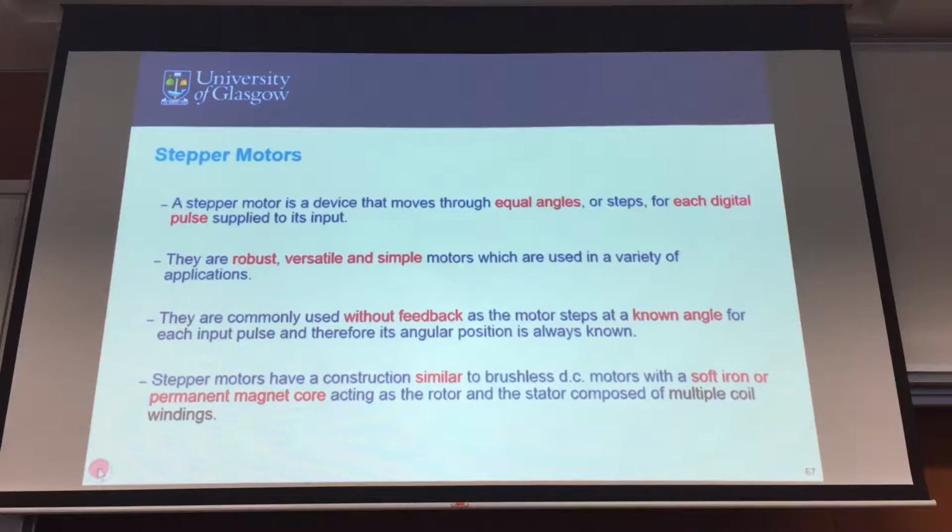So stepper motors are so good in moving to a position of your desired choice by your digital input. So good that it does not require feedback at all. If you were to use a brushless or a brushed DC motor for rotating and you say, I also want to be able to control the position of the shaft, then you need feedback.